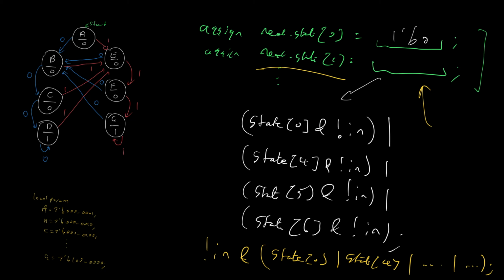As an exercise, if you're keen, you can go to Quartus, you can code up this finite state machine in canonical form, you can then have a look at how many logic elements are being used, and you can have a look at Fmax to see the fastest it can run at. Then, in that implementation, you can simply change your localparam to use one-hot encoding.